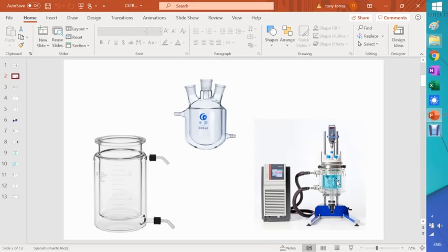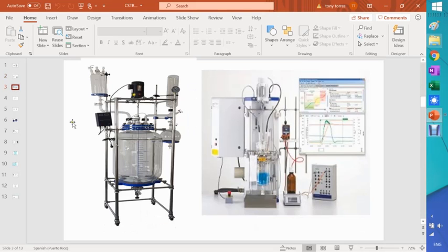What if situations, like what if I don't have enough cooling and there's a secondary reaction here that will kick in a very high exothermic reaction. So things like that can be analyzed with this. Based on that concept, I used to work in my lab with equipment like this one. This is what we call the RC1. This is a pilot scale type unit.